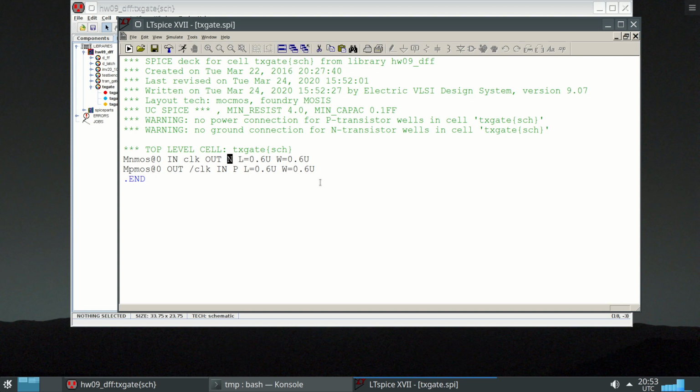This term right here, we should have an extra thing. This is an NMOS transistor. It should be GND. We really want the body of our NMOS transistor connected to the substrate. Well, that didn't come into LTspice, which means Electric did not write this file properly. It only gave us a 3-terminal NMOS instead of a 4-terminal one as it should have. LTspice is expecting a 4-terminal MOSFET.